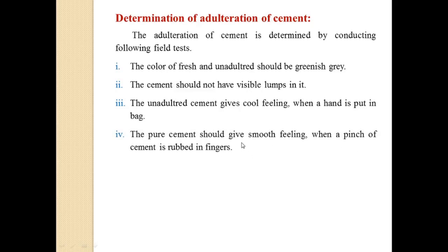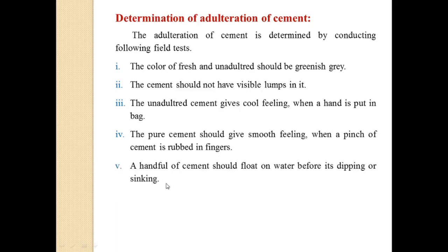Okay, if we are taking the cement in the fingers and rubbing it, it should give a smooth feeling. If it gives a gritty feeling, it means the adulteration may be fine sand or silt content. Next, a handful of cement should float on the water before sinking.